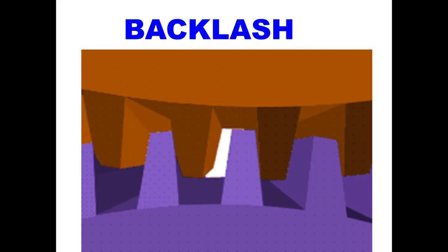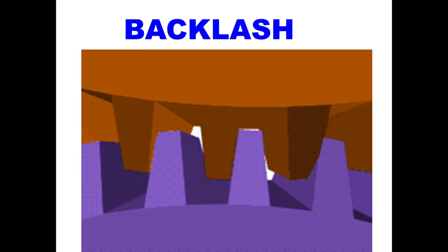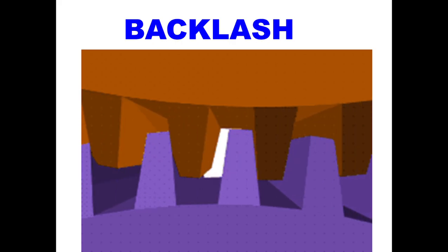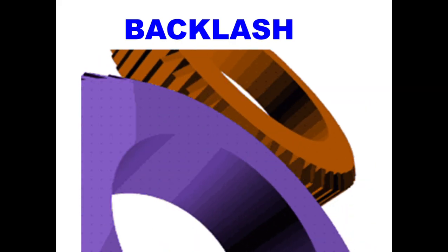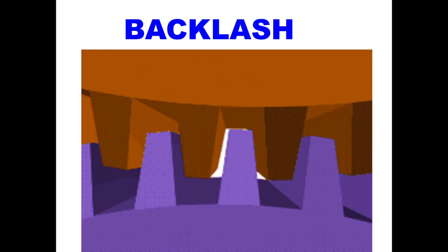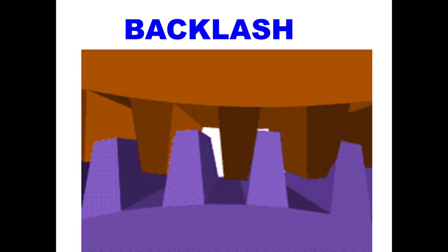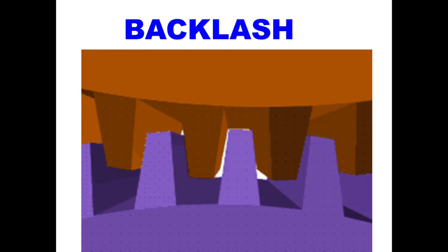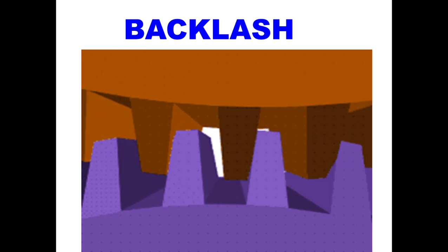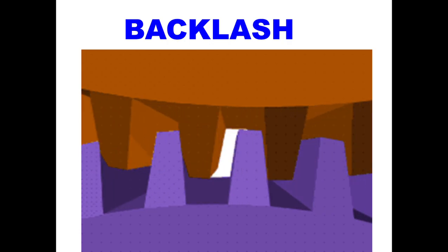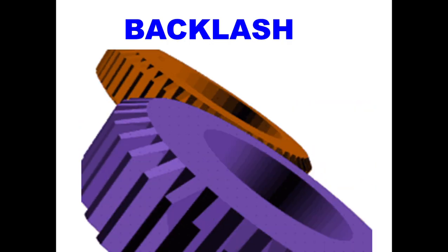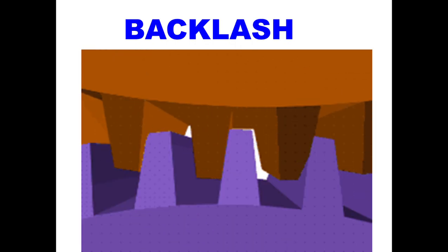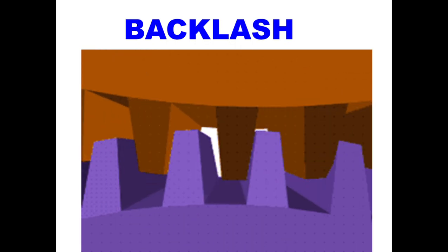Okay, so when we speak about backlash, you must know that backlash in gears refers to the amount of play or clearance between the teeth of mating surfaces. So it is the amount of clearance that we have between the mating gears. It's the distance between the tooth flanks when they are in mesh. This lost motion can occur due to manufacturing tolerance, wear or misalignment. So there can be different reasons because of which the backlash can be there. That is a separate aspect.